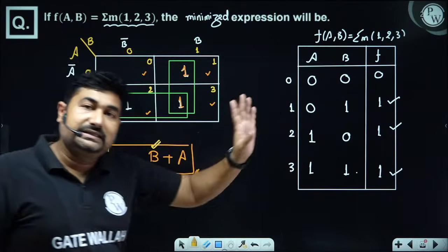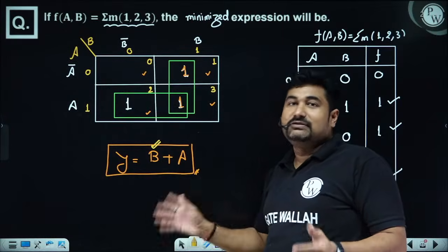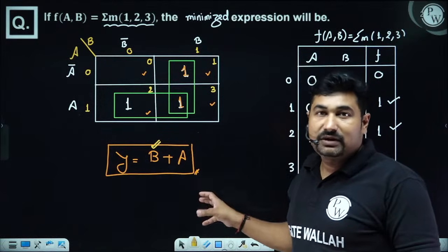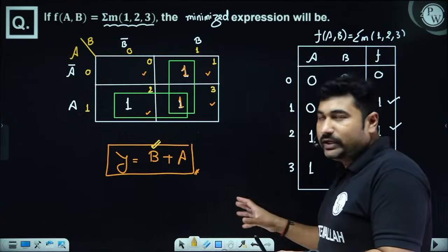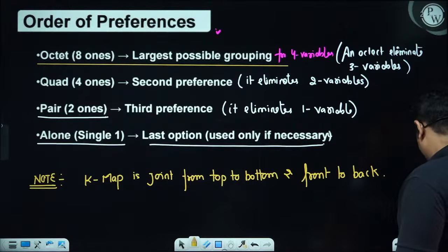All prime implicants are implicants. Is it okay? So these two are implicants as well, but they are prime implicants, the product terms obtained from the K-map which cannot be further minimized. So till now we know about the implicants and prime implicants. Hoping all of you are able to understand up to this part. Great. Let's have one more question to understand it in a better way.